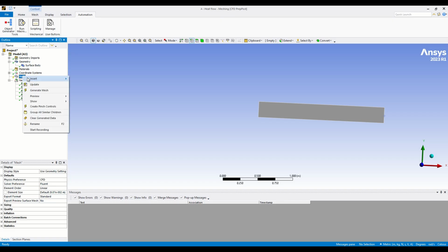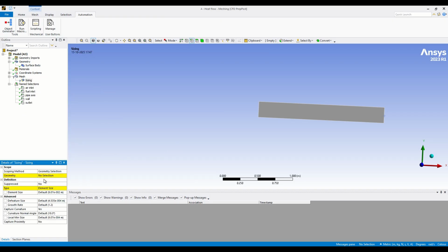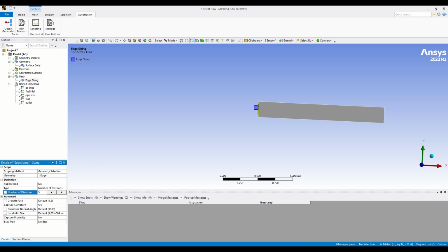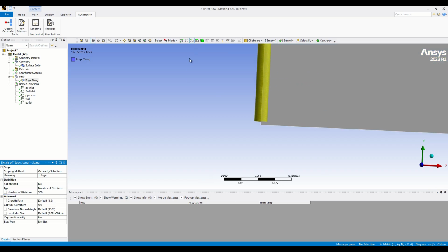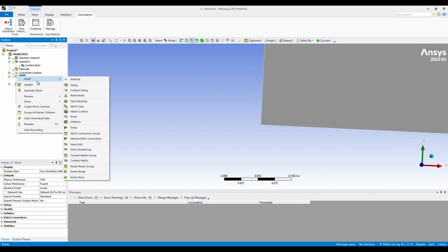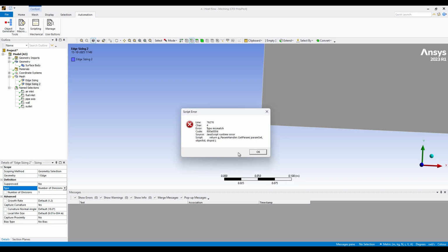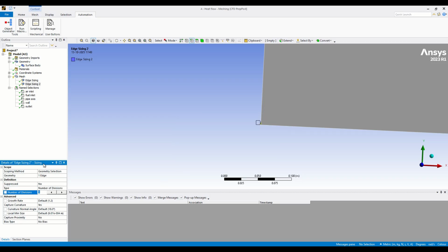Then for meshing, you have to give meshing by divisions. Insert method sizing. In that sizing, on the left-hand side give 500, which is the number of divisions. It is split over here, as you can see after zooming. Then you have to do it again. In the bottom we have split it, so select that and give the number of divisions as 10.